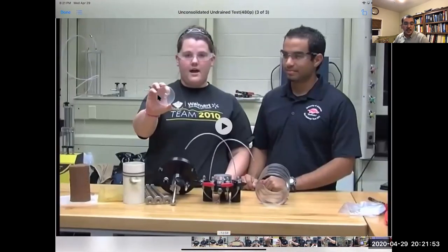So these two will be one on top and one on the bottom, and it's kind of just like a plastic cylinder, I guess. You can put the soil sample on top and it'll be straight, so you can apply the load uniformly to the sample. And this is the top, and you can see it has a small circle inside of it, and that's where the piston will go to apply that major principal stress.